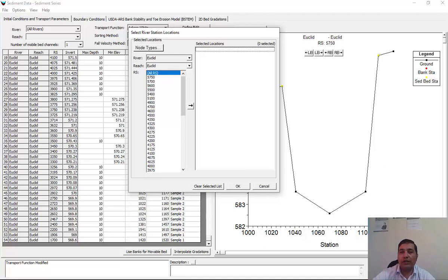One-dimensional morphodynamic models don't simulate the helical currents and mobility inversions that maintain pools, because 1D models don't simulate the three-dimensional pool maintenance process. Cross-section average models convert the larger cross-section area of a pool cross section to low-velocity transport nodes. Therefore, 1D models tend to deposit in pools.